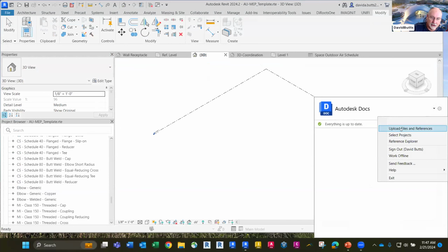If you're doing Revit and you're trying to move from an old project to a new one, you can copy the AutoCAD files all day long. You can go into that ACC Docs folder and zip up all the CAD files into a zip file. I use 7-Zip for that. Then copy them over to the new project location under that same shortcut in File Explorer, and extract that zip file and tell it to go back to the same folder, and it maintains that structure. So as long as you're using relative XREFs, it's clean as a whistle to copy this stuff over.